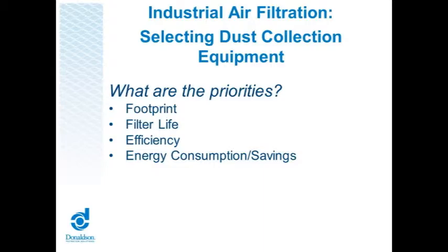And last and probably the biggest one is energy savings. So I don't want to put a collector out there that's going to run a 50 horse fan when I only need 20 horse, and I'm constantly using that 50 horse and draining money out of my pocket for no reason. So having a good idea of what I need and exactly what I need will help me keep my energy consumption down, or keep money in my pocket at the end of the day.